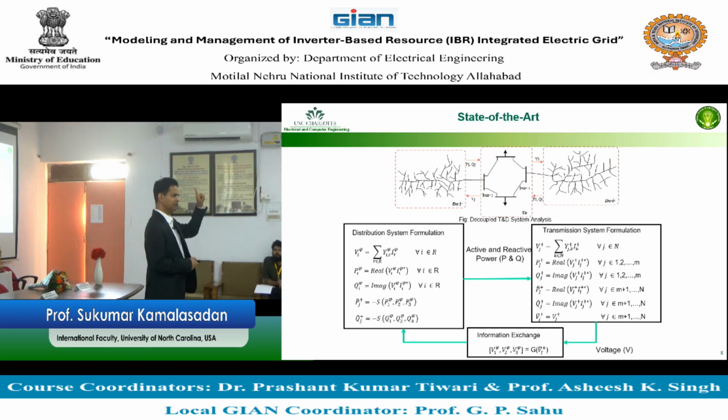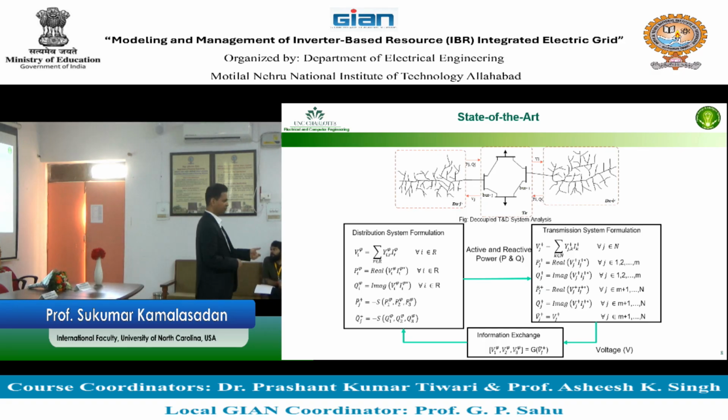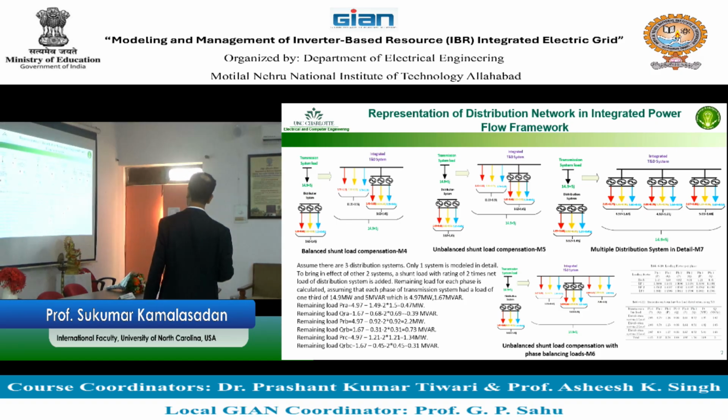One thing which is important to do that is you should know this power. How many distribution systems are connected at this point? You don't have an idea. Only known is the power on that spot load, right? If I have a distribution system connected at 5 megawatt, on the transmission end it may be 25 megawatt, 30 megawatt, because there will be multiple distribution systems connected, right? So you've got to come up with a method to aggregate the distribution system power to the transmission system power.